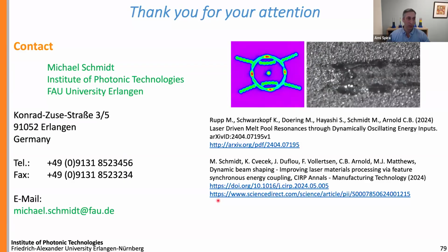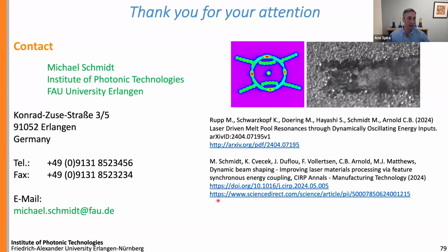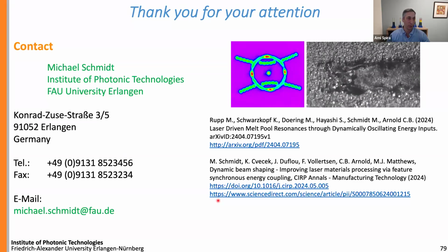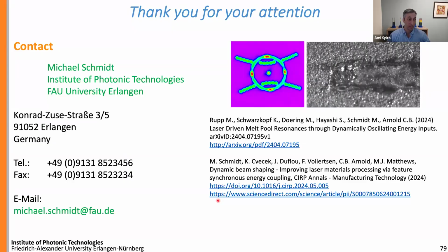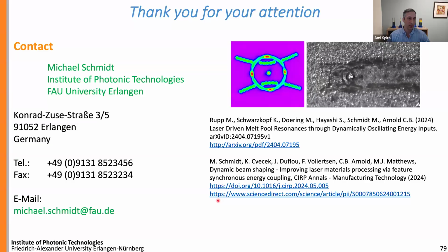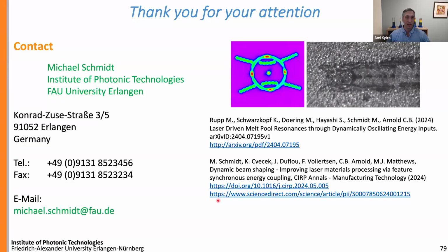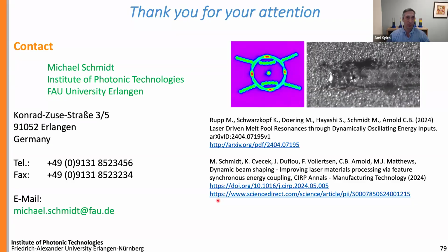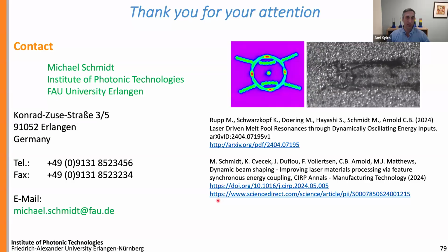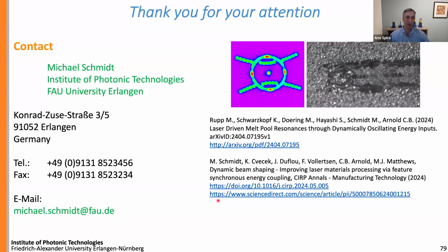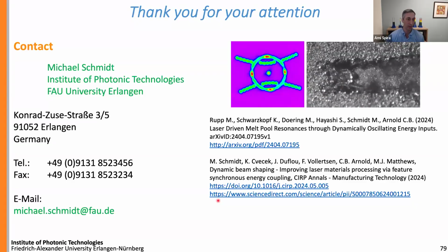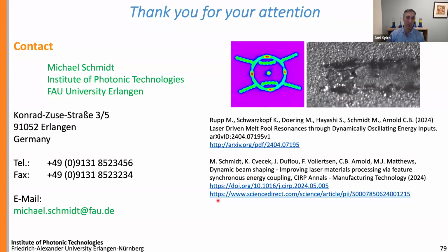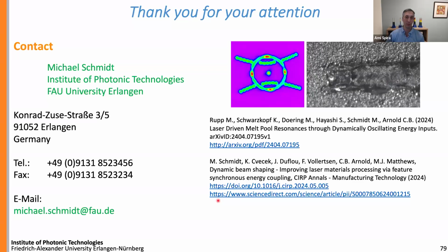And one more question, if you don't mind, I will take this one. The question is, has DBL been tried in laser metal cutting of thick sheet metal to see if this improves surface finish and quality of the cut? I can say that we do know of users who have used the dynamic beam laser for cutting. In general, there's not a strong business case to use this very high-end laser for cutting with the existing solutions out in the market, but from the trials that were done, it has definitely been able to see the influence on the roughness of the cut with different beam shapes.